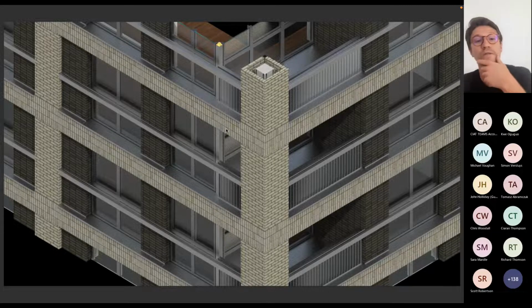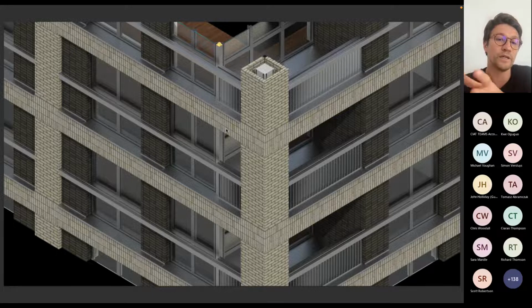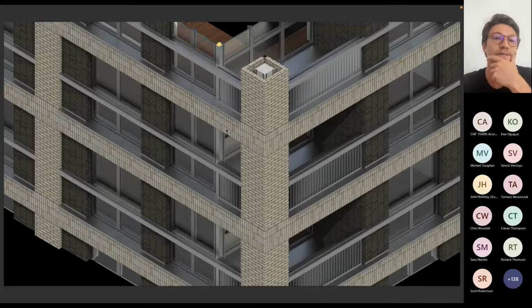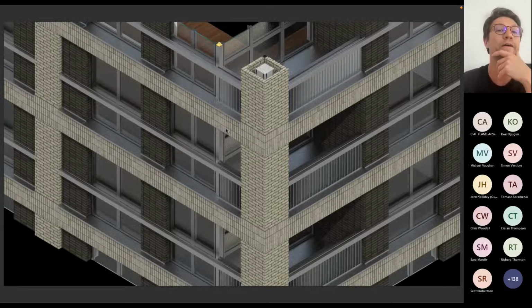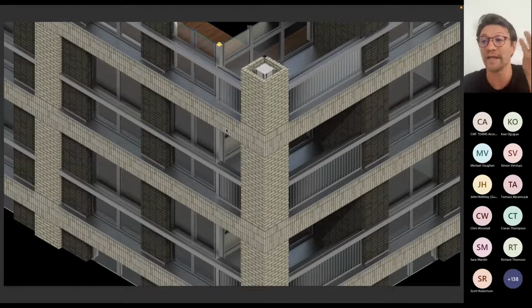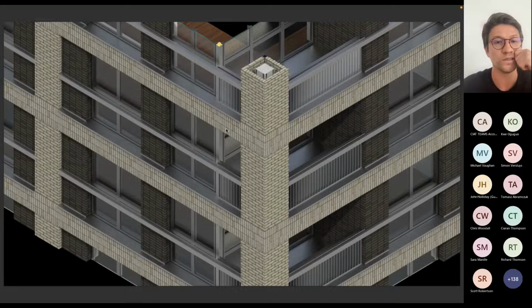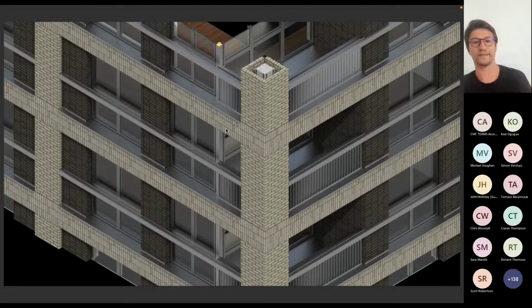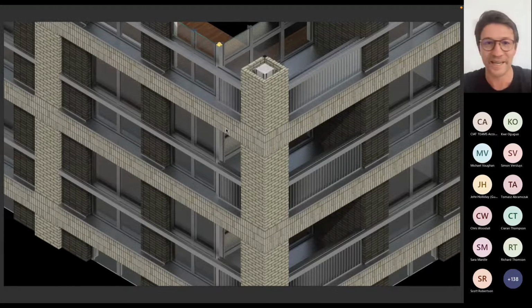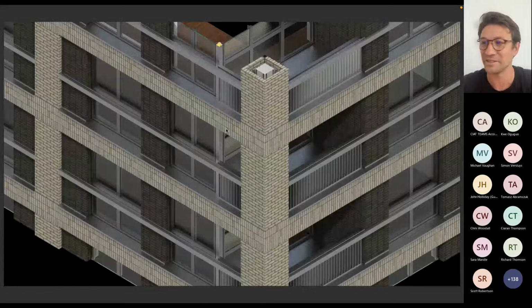Today, we are going to be looking mostly at this bay, the one that you see on your screens right now, and we are going to achieve it in 3 different assembly methods. Namely, it is masonry veneer, brick slips, and precast. And we're going to conclude with a case study, which has a mixture of all 3 of these facades. There'll be no drawings, there will be no text on the screen, just 3D details the way we like it, and just some verbal narrative to it.